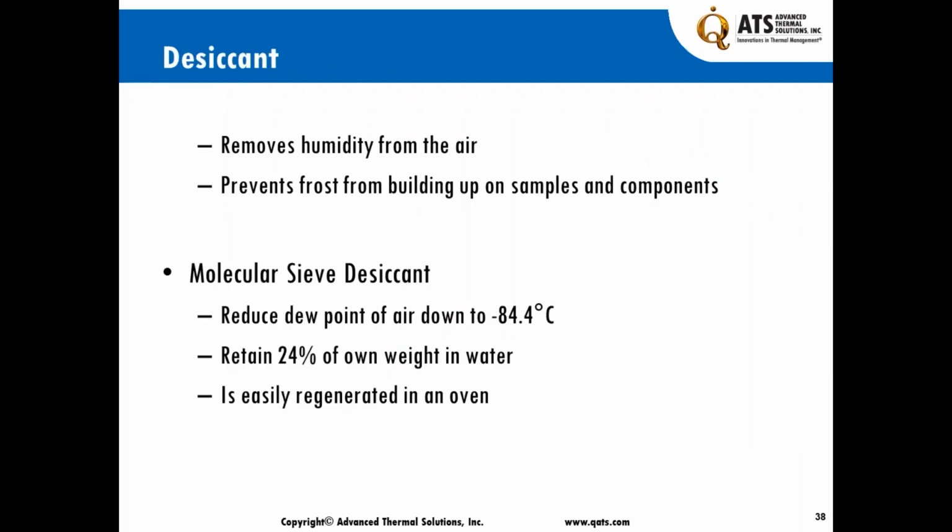So the desiccant was a critical factor of the whole design. Remember, we had some requirement for visibility and lack of frost. Frost has two effects: both blinding the sight and also potentially impacting the integrity of the cells. So the objective of the desiccants is to remove the humidity from the air and prevent frost buildup on the samples and the components.